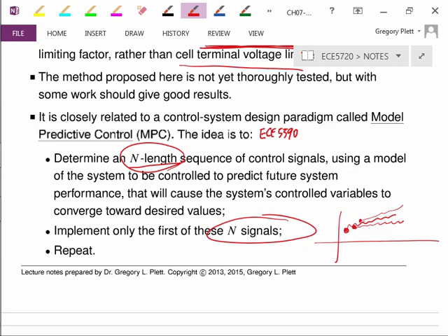especially because what we're going to consider are some hard constraints that I cannot violate. If I don't look into the future long enough, I may not realize that I'm coming close to a constraint, and then because of the momentum of the system dynamics, I may actually exceed that constraint because there's no other thing I can do. Model predictive control looks into the future, allows me to see a hard constraint coming and then to gently come up against that constraint without exceeding it.